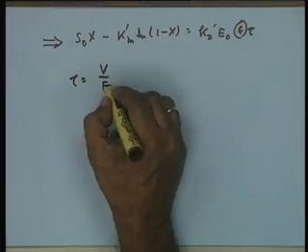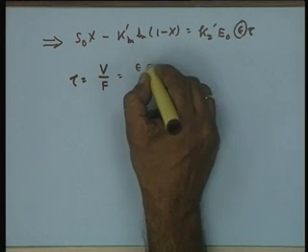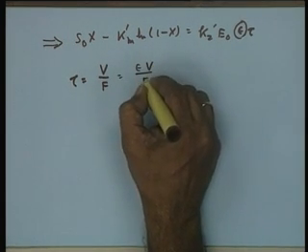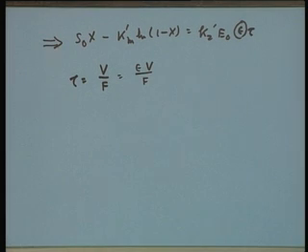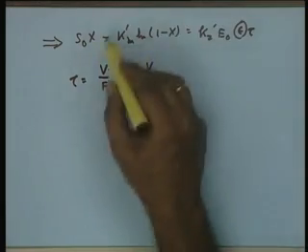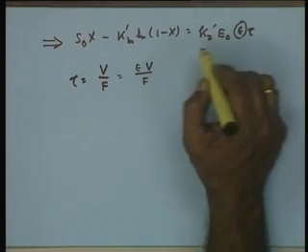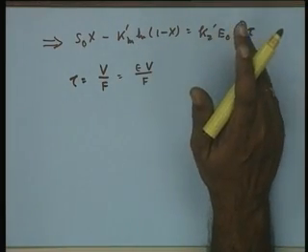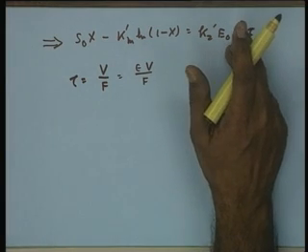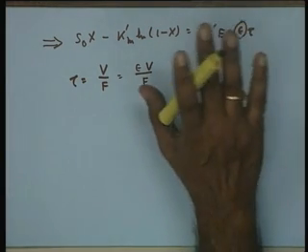Therefore, this tau term is multiplied by epsilon. While as we defined earlier tau as V by F, in the case of a packed bed reactor we define tau as epsilon V by F. For a CSTR or for a stirred batch reactor, the magnitude of epsilon is 1. So, essentially this gives you the reactor performance for a plug flow reactor following Michaelis-Menten kinetics.